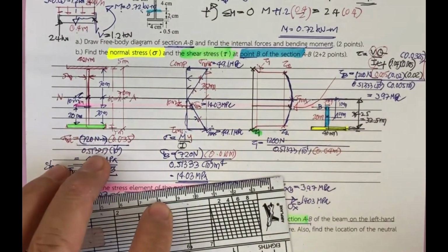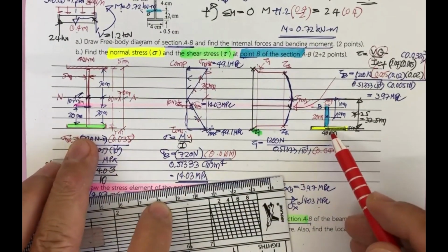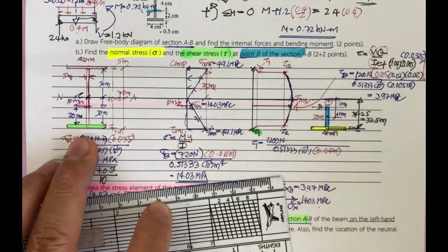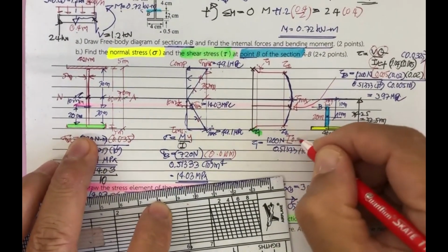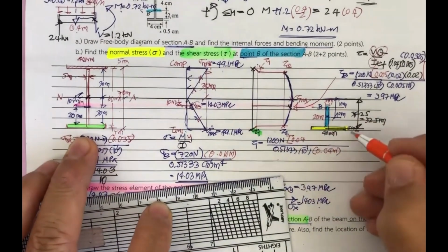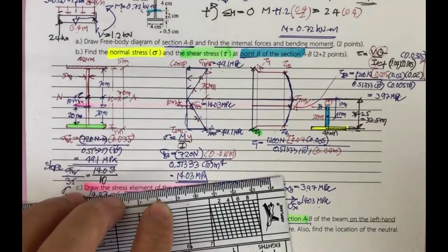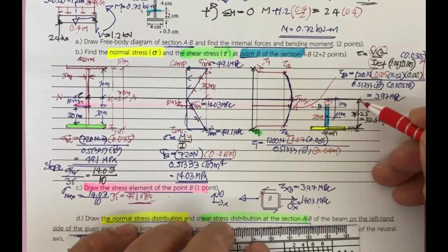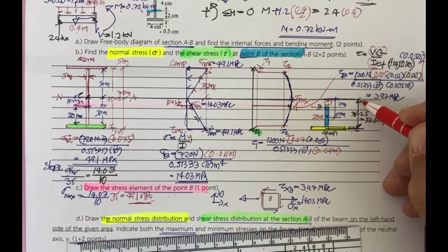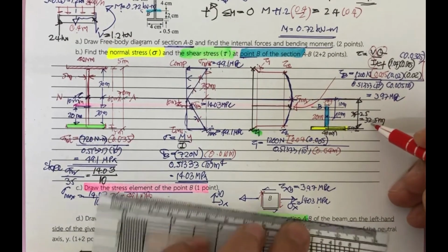Okay. So the Q of this green and the Q of this yellow, they are going to be the same. So the area here, 0.04 times the thickness, 0.005, and then the distance from this one to this one, right? So it's going to be 0.0325.